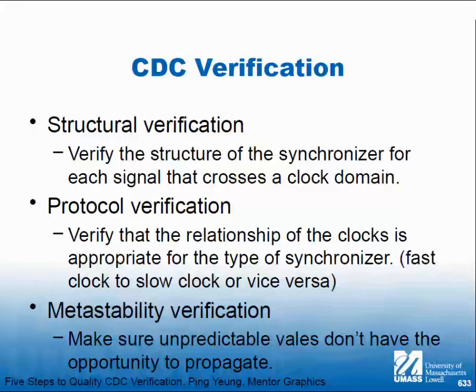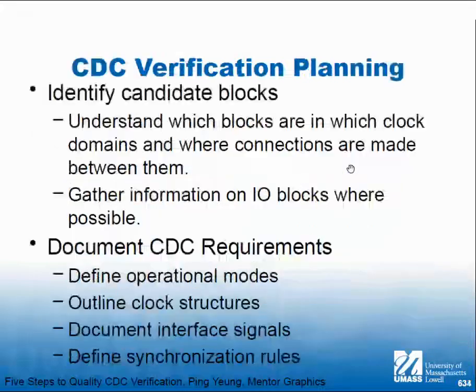How do you test that? It's hard. How do you make sure it's still in there? You spot check for it. Meaning, if you put that in a synthesizer that didn't know what it was doing, it would simply take 2 of those flip-flops out, because the D input of all 3 flip-flops is the same signal.